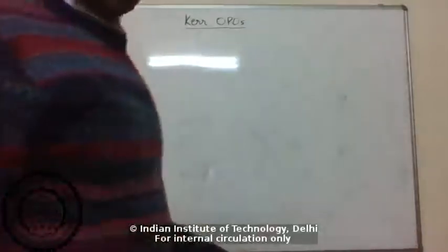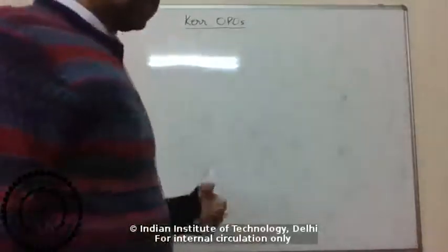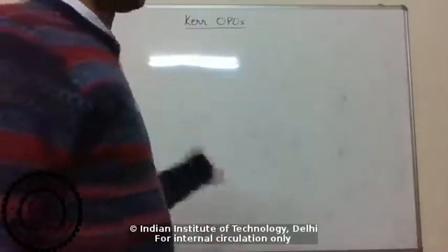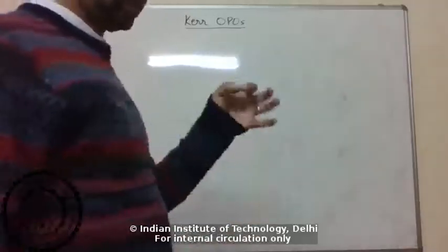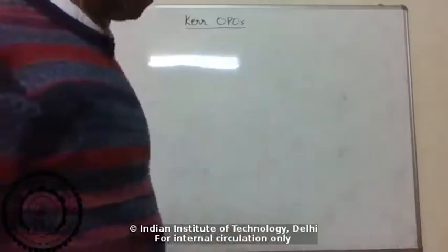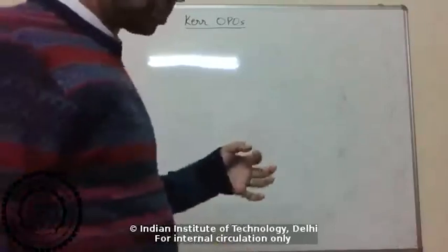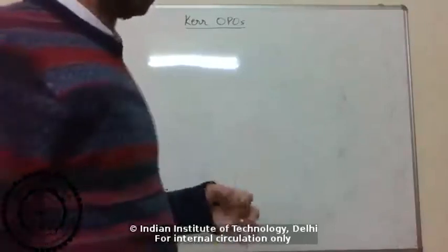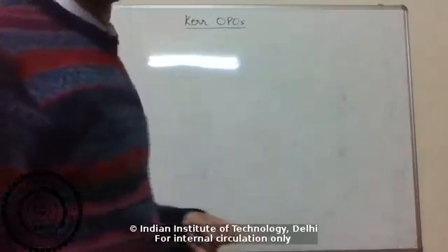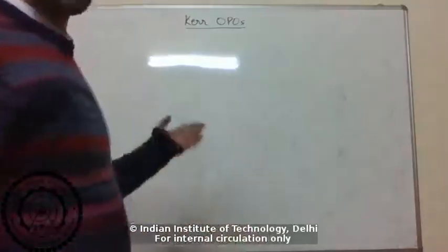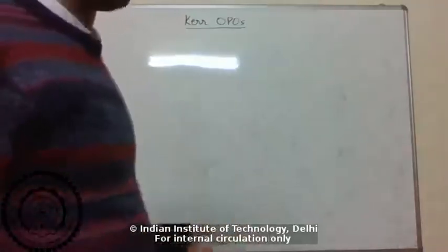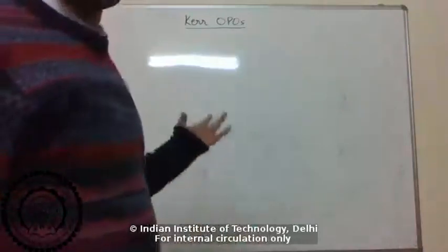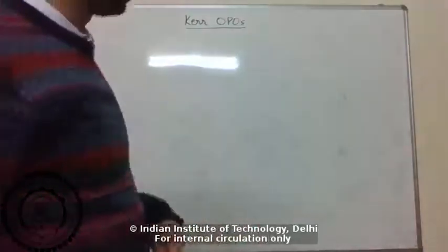So typical materials people use nowadays are silica. Of course, optical fibers are made out of silica, but people now can make really small cavities like microspheres or these microtoroids or even micro rings using silica, very high quality, right? So the quality factors are 10 to the 6, 10 to the 7, 10 to the 8, that kind of range.